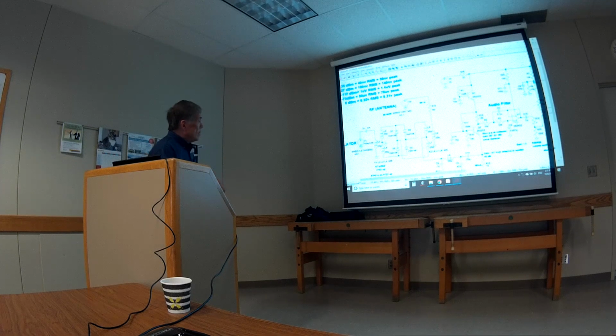Now here for the local oscillator, I'm going to set that to 7 megahertz plus 600 hertz and 1.5 volts peak, so 3 volts peak to peak. You always want the local oscillator to be pretty husky compared to the antenna signal. And this is very simple. It's not the same mixer that we had before, but I'm doing a diode ring mixer, which is very common. I love diode ring mixers. They're very clean. They're still widely accepted as some of the best mixers around.